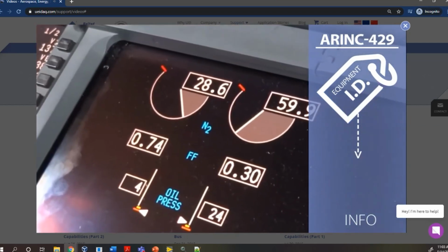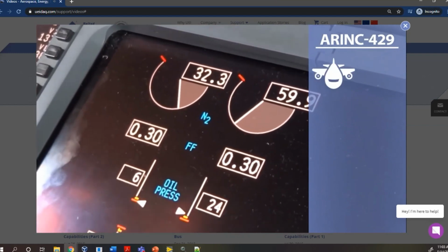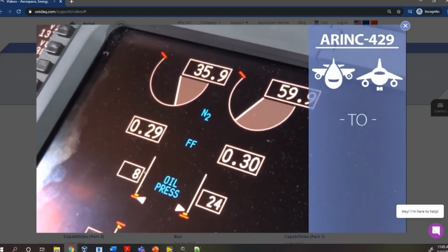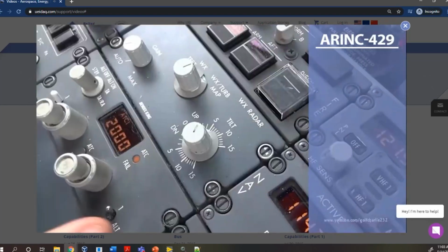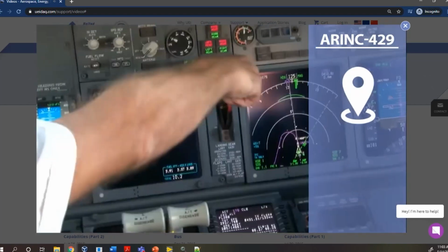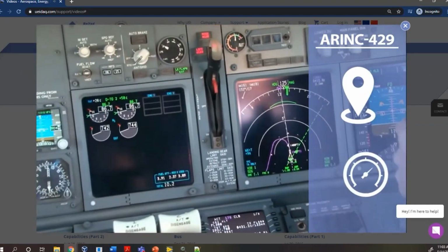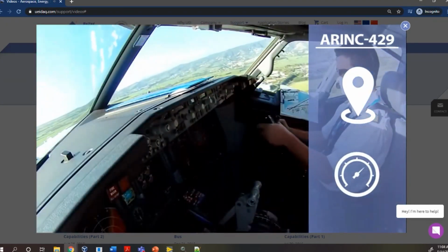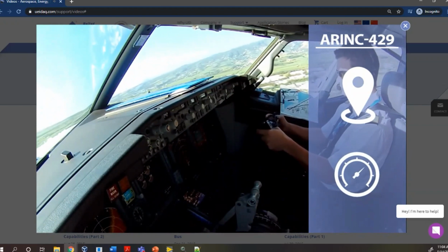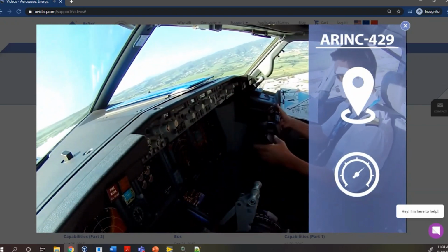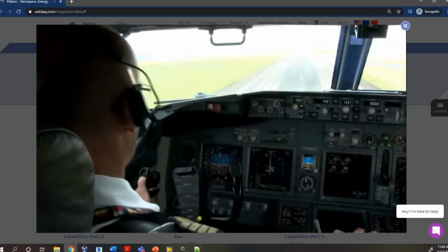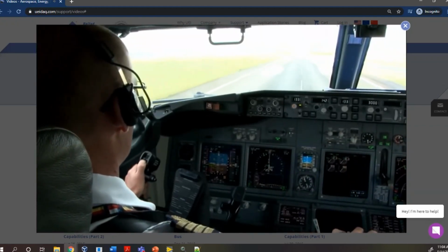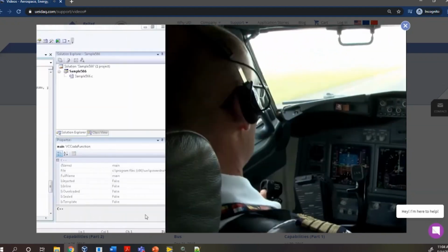The ARINC429 standard gives guidance so different manufacturers can have the same type of equipment giving the same type of labels. There are a limited set of labels, so label 409 on a GPS may have a different meaning than label 409 on an altimeter. This is possible because the 429 standard also allows for an equipment ID field, so you can correctly interpret 409 for different pieces of equipment.